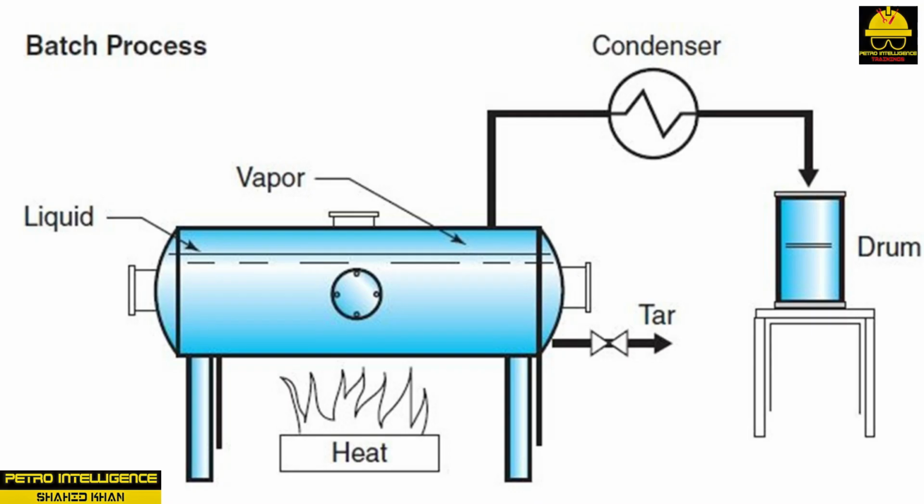Batch distillation, as shown in the picture, is the oldest distillation process. The raw materials were mixed together and charged to the still. During phase 1 of the distillation process, heat was added to bring the mixture to a boil. The overhead vapors were condensed and stored as final product. At the conclusion of phase 1, the overhead line was switched to a new receiver, and the temperature was increased. When the receiver was full, the process was repeated, and the heat was increased incrementally until the batch run was complete. Product quality during batch distillation operations was very poor. Frequent receiver changes wasted time and money.